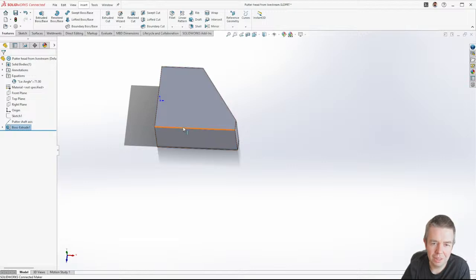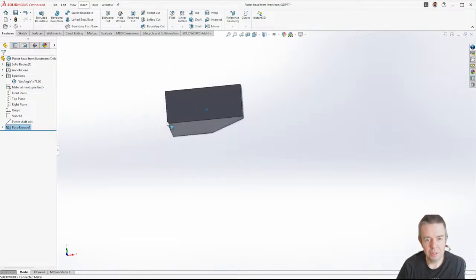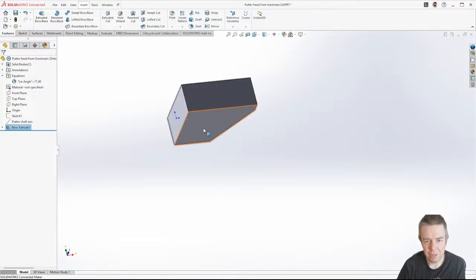So we're going to either chamfer or fillet all of these corners, but we also have to do something specifically on the bottom of the putter, because a flat surface there will catch on the grass a lot, and it will really annoy the user. I built a putter with a flat bottom in order to understand why no putters have flat bottoms, and it's totally terrible.